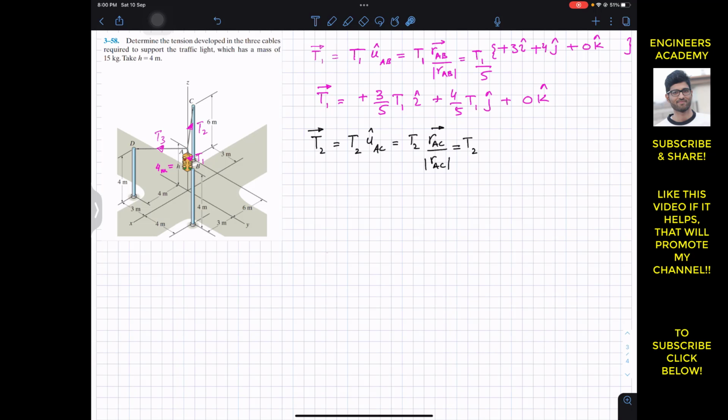So now the distance between point A and C along the x axis is this distance, right? This pole is at a distance of 6 meters from this particular point. So this means that the distance between point A and C along the x-axis is 6 meters. So from A, we need to travel 6 meter distance in the negative x direction. So we can write that this will be minus 6i.